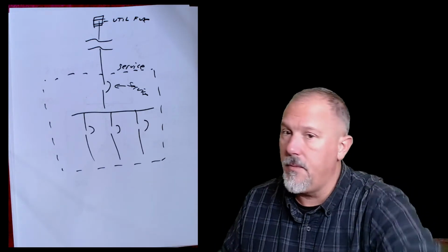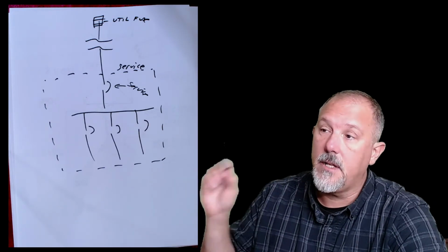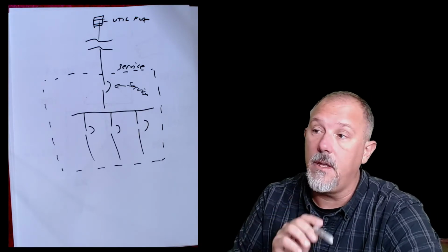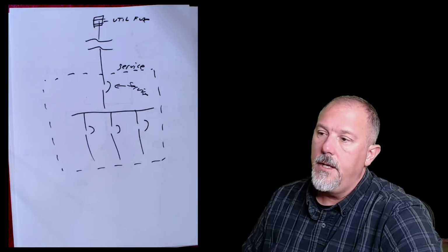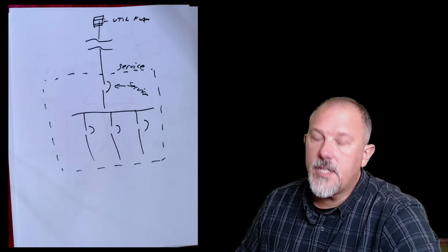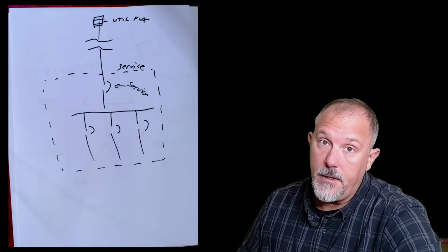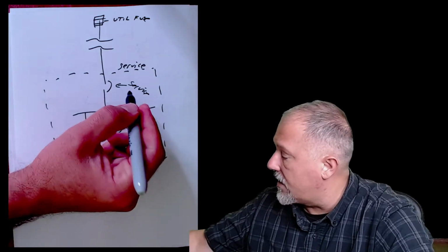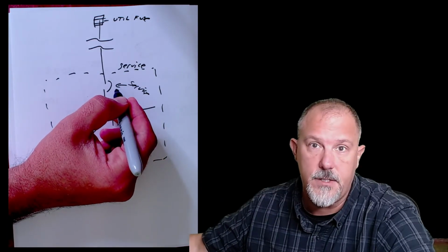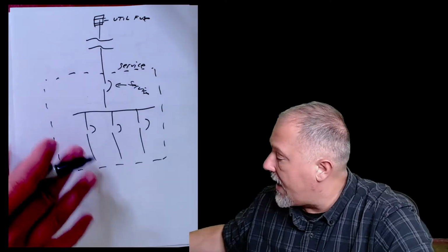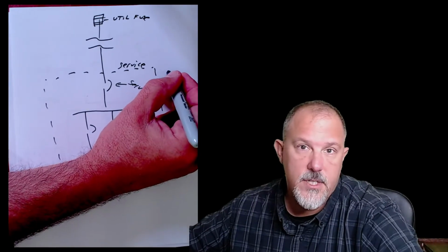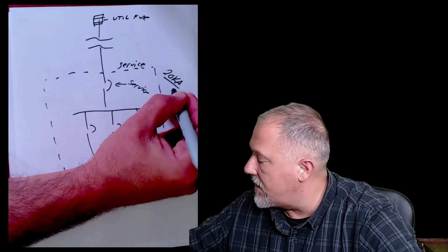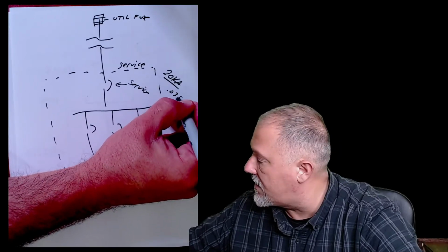You could be right. But putting in the clearing time, putting in the available fault current, going back to what was in 2020, I think puts the electrical worker at risk, in my opinion, if they follow that logic, because what they're going to do is put the clearing time of this service overcurrent device. So what would that label tell you? Say the label is 20 kA and the clearing time is 0.03 seconds.